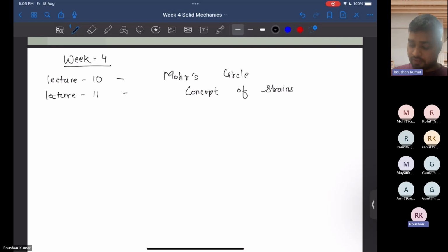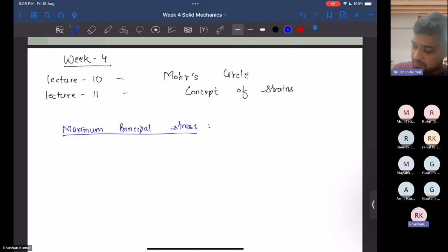through the Mohr circle, and the formula for that is given by, so maximum principal stress is given by sigma is equal to (sigma xx plus sigma yy) upon 2 plus R cos (2 phi minus 2 alpha), where R is the radius of Mohr circle.